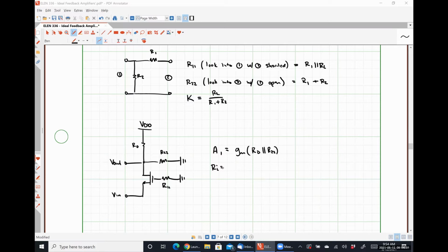So the current through this thing is controlled by the gate source voltage, VGS. Vin is Vs. The other part of that is Vg. So Vg is what we're considering our input terminal for this guy, because that's where we're applying the feedback signal. Exactly right. Another way to put it, Mr. Greer said, it's the port input, not the system input, which is a perfectly great way to look at it. So that's why we're connecting it to the gate.